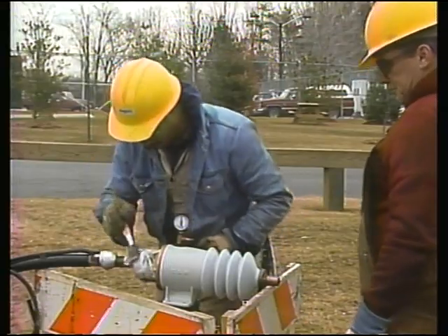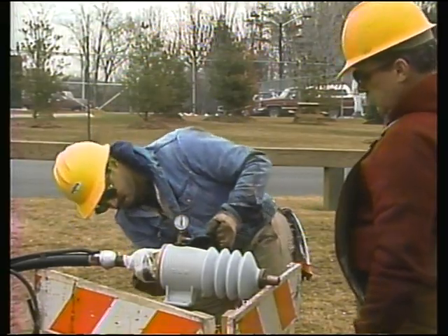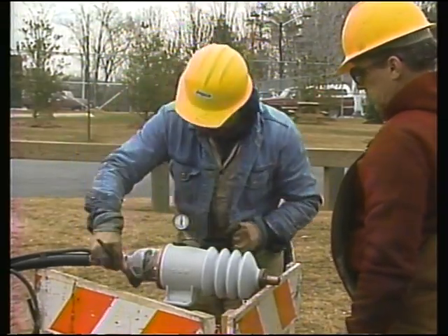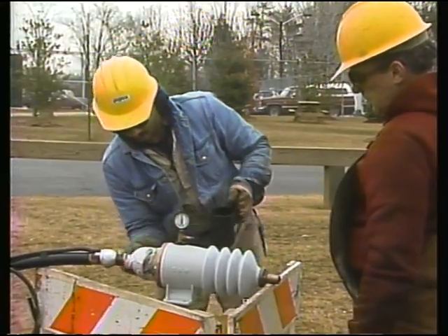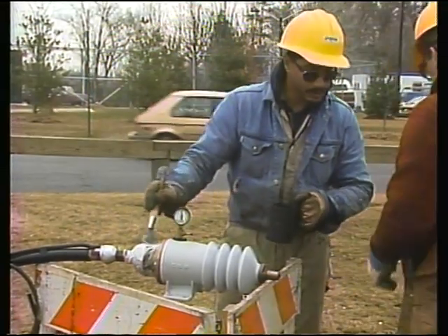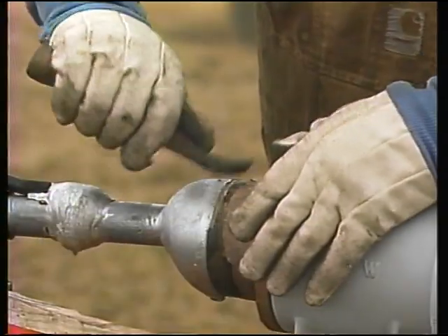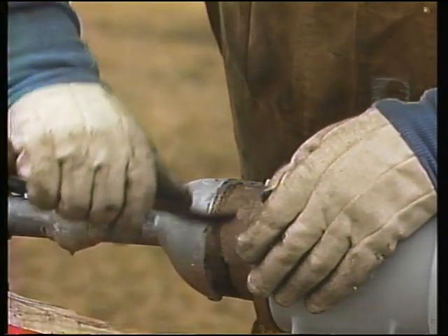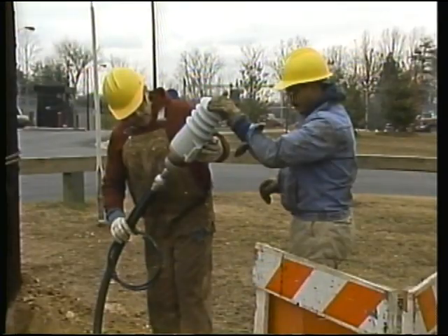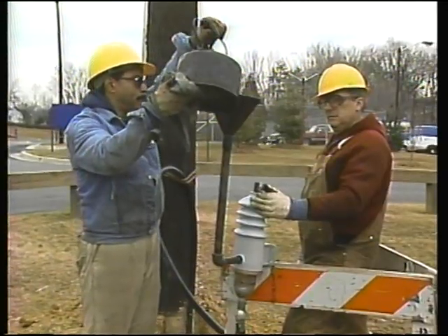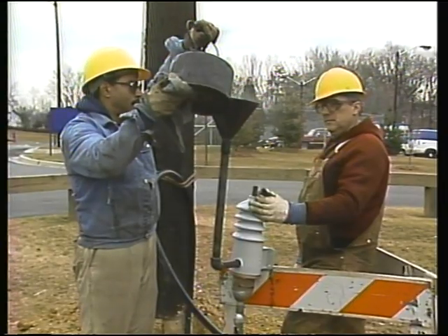At this point, the procedures for this company call for the terminator housing to be filled to a specified air pressure and coated with a soapy solution to check for leaks. Then the solder restraining tape is removed. The final step is filling the terminator with a sealing compound. To do this, the cable is placed upright and the hood nut assembly is removed. Then, a pipe and funnel assembly is installed.